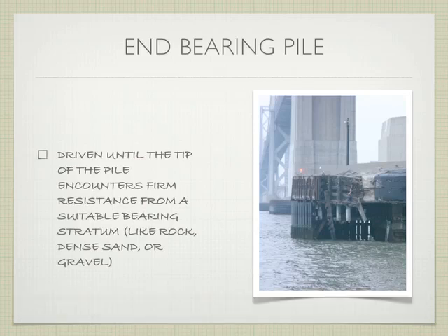It's driven until the tip of the pile encounters firm resistance, right, from a suitable bearing strata, right, like bedrock or something like that, right? So you just keep driving it, okay? It could be dense sand, it could be gravel, it could be something like that, right? So that is an end-bearing pile, right? It has to be driven until it reaches something solid, okay?